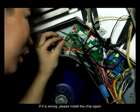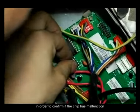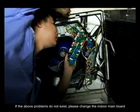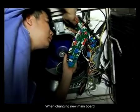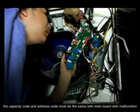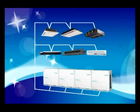If it is wrong, please install the chip again, or replace the chip of the malfunction unit with the same model chip in order to confirm if the chip has malfunction. If the above problems do not exist, please change the indoor main board. When changing to a new main board, the capacity code and address code must be the same as the main board with malfunction.